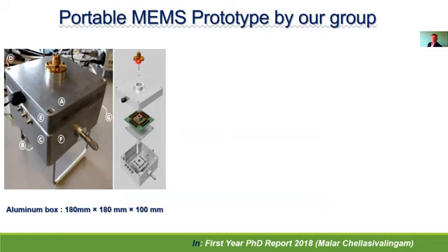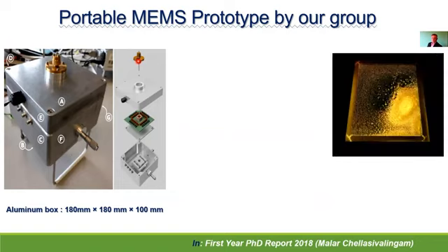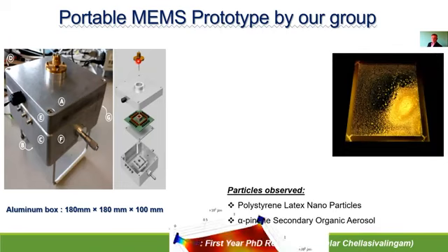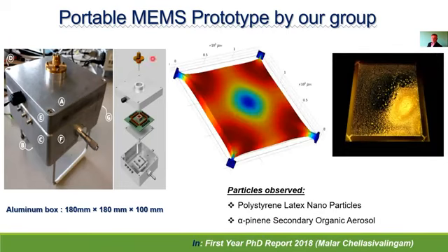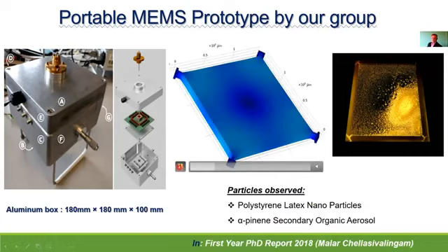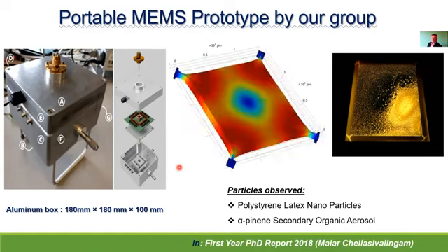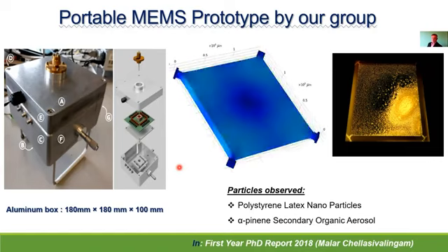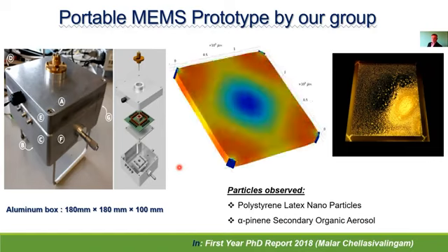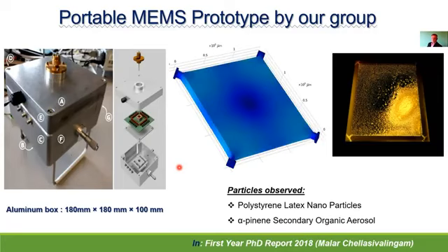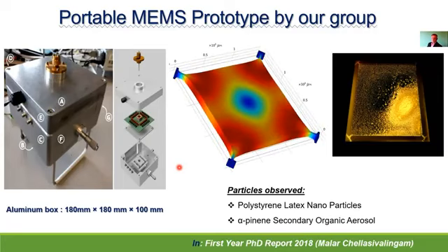Previous work in our research group has focused on the square plate piezoelectric bulk acoustic MEMS resonator operating in its square extensional mode. The square extensional mode expands equally in all the 4 directions, with the red points being the sensitive points of the resonator. So if you note carefully, in all these MEMS sensors, the resonant frequency shifts based on the mass of the particles deposited on the resonators. This is very important because the current engine emissions or the air quality standards that have been set are mass-based.